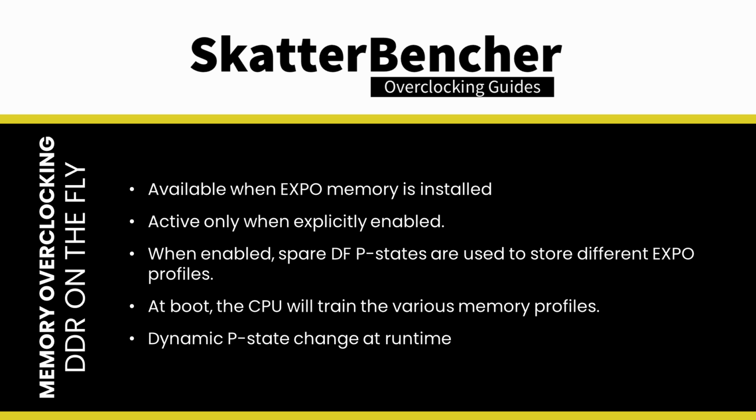While DDR on the fly OC mode is available in the AMD BIOS, unfortunately I could not get it to work at the time of writing. I can enable the function, but the system will not complete post, resulting in the need to clear CMOS. This function may work on other motherboards, BIOSes, or with different memory, or with future AGESA updates.